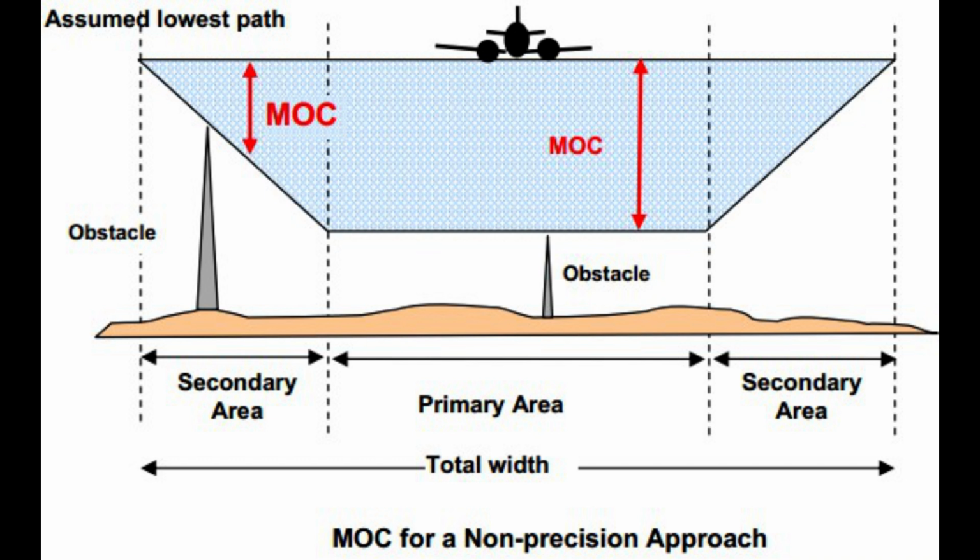The pilot/aircraft information component of these criteria includes pilot ability to track the radial and the flight track resulting from turns at various speeds and altitudes under different wind conditions. The navigation system information includes navigation facility radial alignment displacement, transmitter monitor tolerance, and receiver accuracy. All of these factors were considered during development of en route criteria.